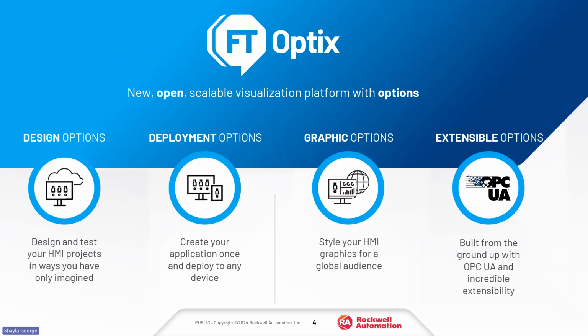And then as far as extensibility, it really extends beyond just communicating to Rockwell devices. So when you think back to View ME or specifically View SE, if you want to communicate to a third-party device, you have to have the use of Kepware, so an additional piece of software for the flow of that communication. With FactoryTalk Optics, that's not a requirement. So Optics does have the built-in drivers that allow you to communicate to Rockwell devices, so ControlLogix controllers, CompactLogix, MicroLogix, both the MicroLogix and Micro800 family.